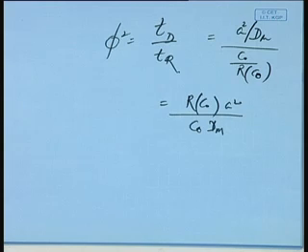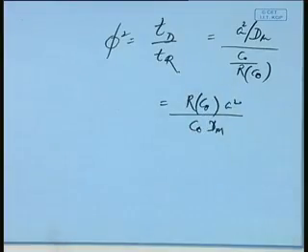What you find here is that if the reaction rate is faster, the Thiele modulus essentially is proportional to the reaction rate. The question is, what is this reaction rate? When you write a Thiele modulus, you write the reaction rate in terms of C naught. What is the concentration? Yes, that is what is typically taken: the maximum concentration, or the initial concentration, or the boundary concentration.